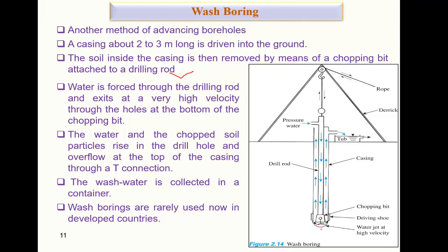So it is cutting the soil here, and you are pressurizing the water here. So what happens? The water and the cut soil make a slurry, a fluid kind of material, right? And while you pressurize more water here, there will be some upward force from the water, and you can see it is going up here, right?